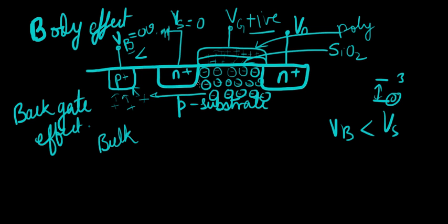And the point at which conduction starts is called the threshold voltage, right? That means, say our threshold voltage was 0.7 volts. And because of the inclusion of these extra negative ions, it's going to go up to maybe 0.75 or 0.8 volts even.